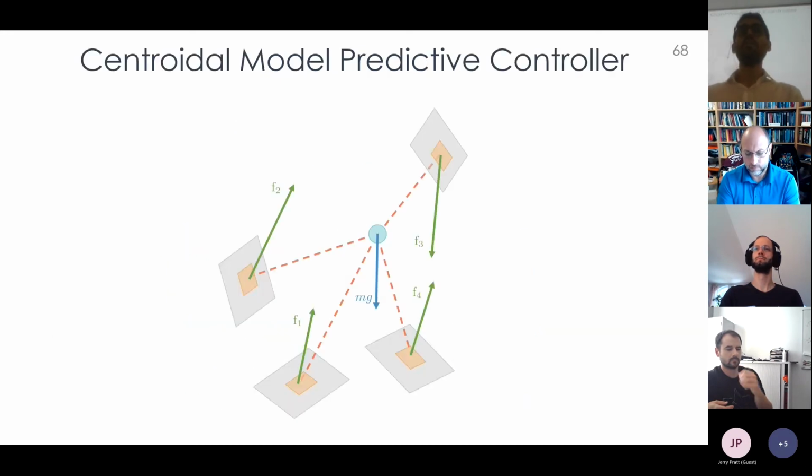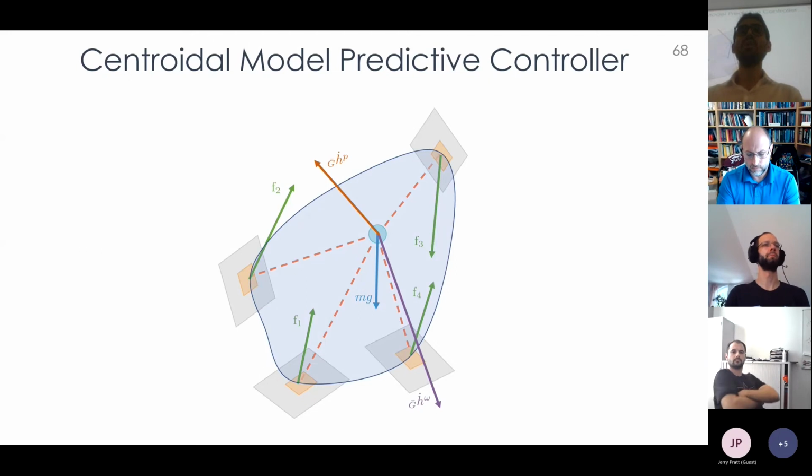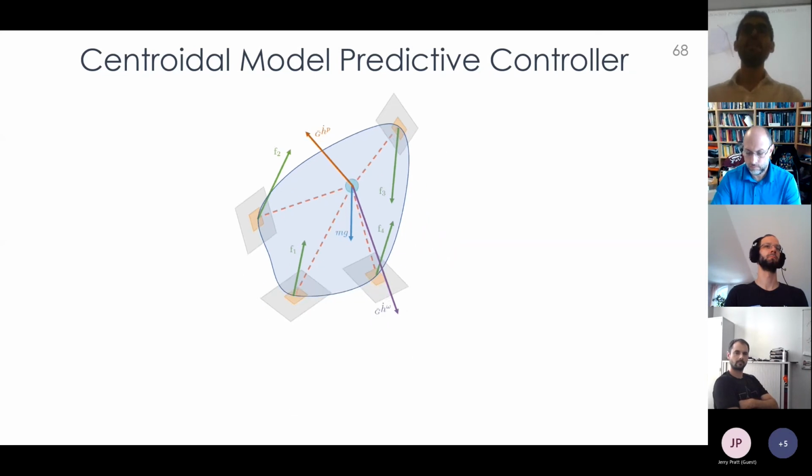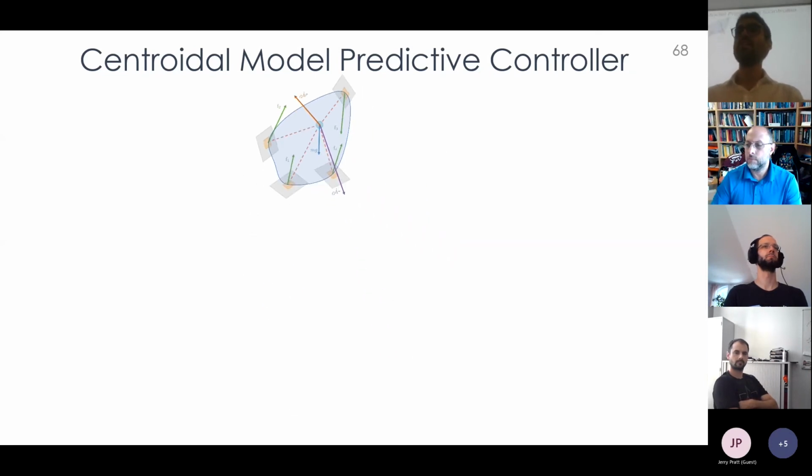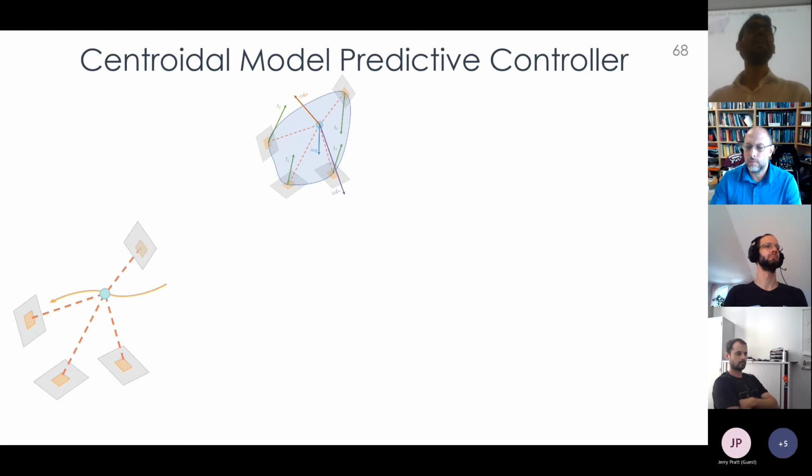Okay, so let's start from a multi-body system. As you know, when this system interacts with the environment, it's possible to find the dynamics of the system and consider the centroidal dynamics of the system. And the main idea here is to have these centroidal dynamics along with a high-level planner for the footsteps. The high-level planner generates only nominal footsteps, position, and location.